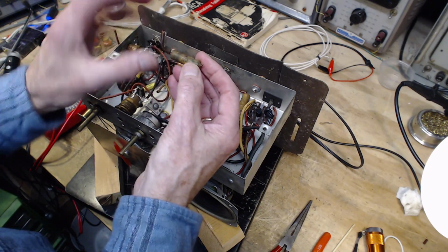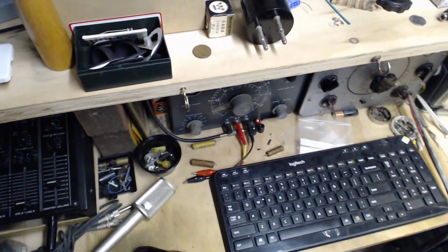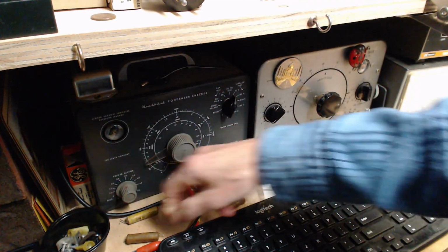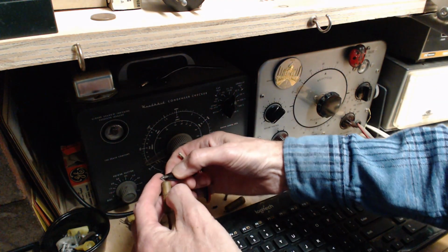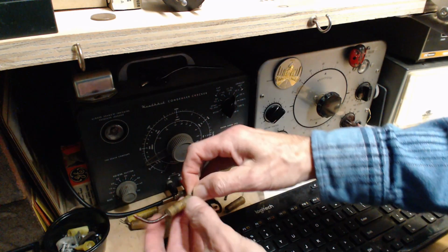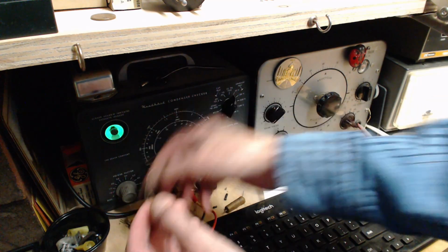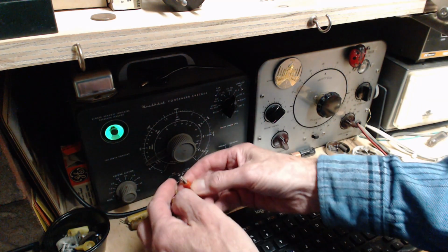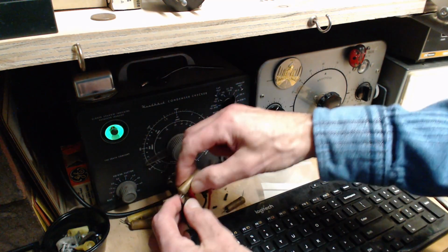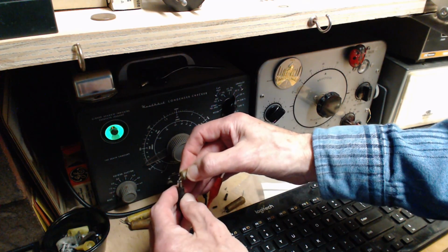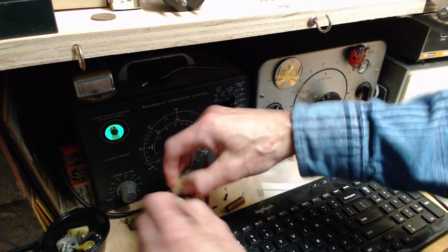Now, is this guy leaky at all? Well, yes. That would be my guess is yes, he's leaky. All the rest were. The question, I guess, is how leaky is it? Now, this is only a qualitative test I'm doing here. I can't tell you how many coulombs per minute leak through this, under a certain voltage. The voltage this capacitor is sustaining is very low, 10, 15 volts at the most. So it's not under a lot of stress inside.